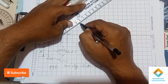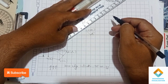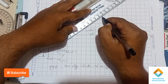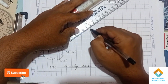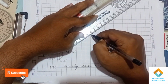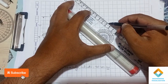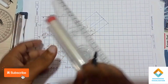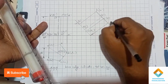Count it 1 2 3 4 5. So till there you have to join. Same way for the axis also. To that reference point we have to draw an axis. Now we can connect from C1 dash, from there you draw one perpendicular line for a length of 50 mm, and again for the D1 dash also you draw one line which is of length 50 mm. You can now draw the top face by joining all these points. Okay, now join the top face, write the top face notations: B dash, A dash, O dash, C dash, E dash, and D dash.